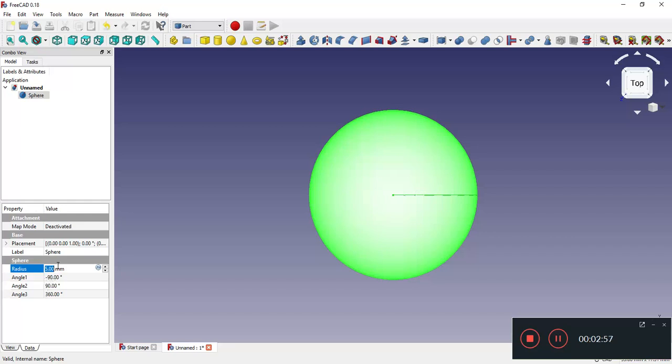But remember, OpenFoam has this funny thing where it is printing in meters, right? So the thing is that with FreeCAD, the STL files that it outputs are always in mm. But there's no unit, so there needs to be a factor of 1000, dividing by 1000.